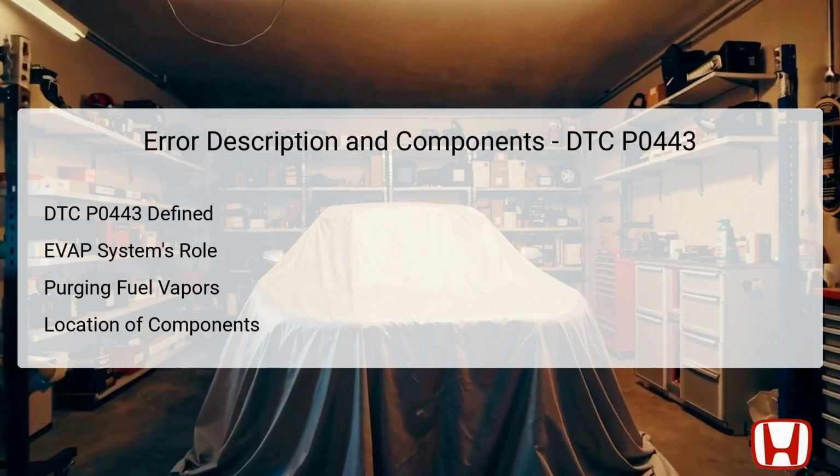When the purge valve fails, it can either remain open or closed, resulting in improper vapor flow. Of note, this valve is usually positioned within the engine compartment, making it accessible for diagnostics. By regulating the amount of vapor reaching the engine, the purge valve optimizes fuel efficiency and minimizes pollution, highlighting its critical role in both performance and environmental impact.